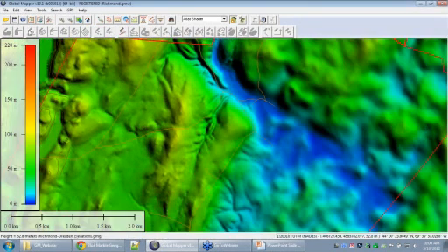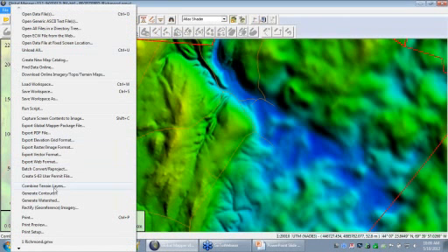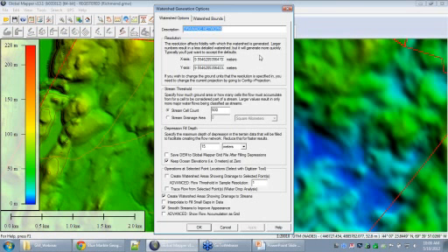So again, I'm going to pan us over to a clean section of terrain here, and we're going to take a look now at a watershed. So basically, if we drop a bucket of water on the ground, which direction is that water going to flow? That's a watershed calculation. So the watershed is going to calculate for us a drainage network as well as areas on the map that allow us to see where water is going to flow together and then form streams.